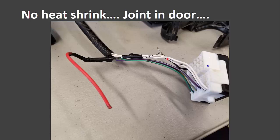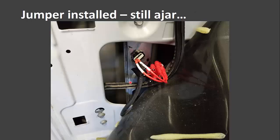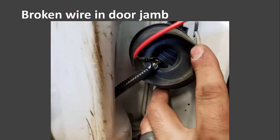So the proper fix here is we de-pinned this wire right here, popped a new pin on and then a fresh wire, and made the butt connector connection inside of the door rather than inside the door jamb. So now we only have wiring in the door jamb, no butt connectors or solder joints.